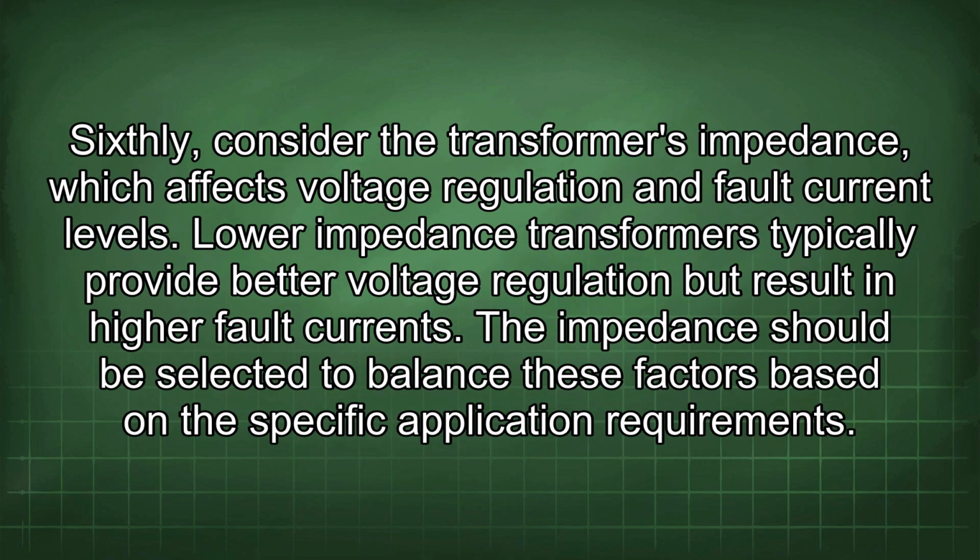Sixthly, consider the transformer's impedance, which affects voltage regulation and fault current levels. Lower impedance transformers typically provide better voltage regulation, but result in higher fault currents. The impedance should be selected to balance these factors based on the specific application requirements.